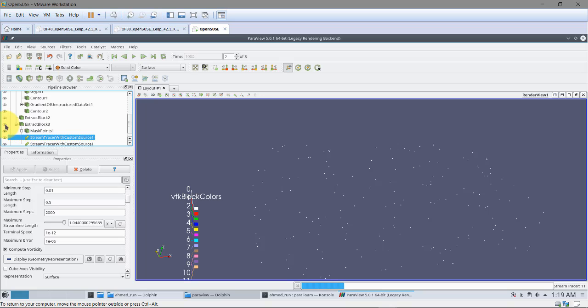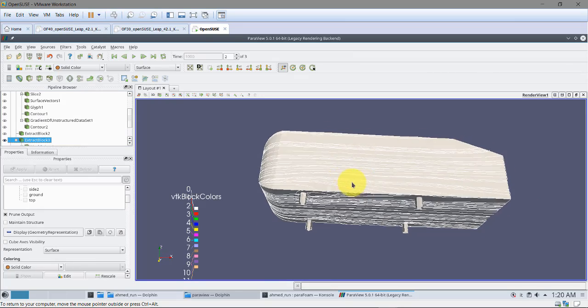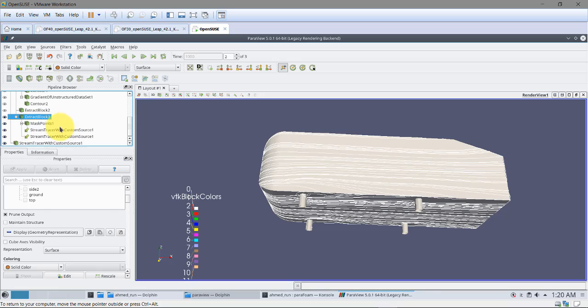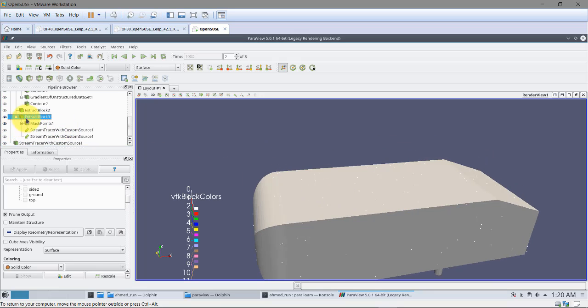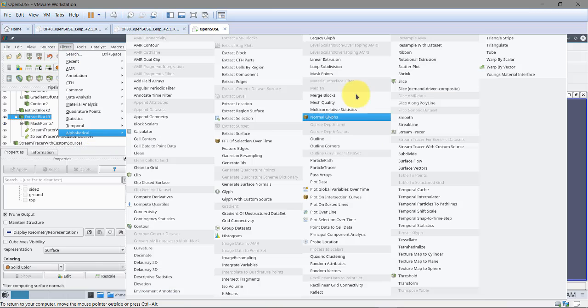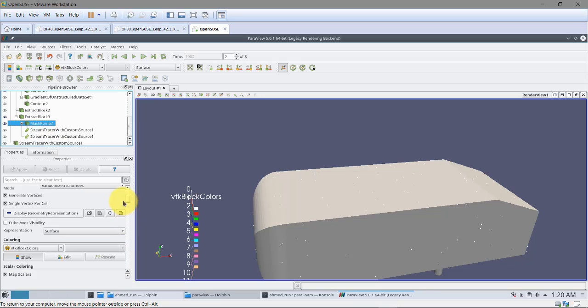As always, we have many filters. It's a very complete tool. Okay, we have many sensors in ParaView. And you see that I'm releasing the streamlines only from those points. So to create this one, again, you go Filters, Mask Points. Okay, you can do that one, and you will have many options.